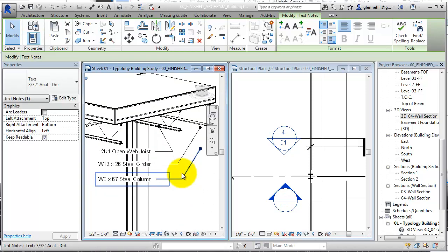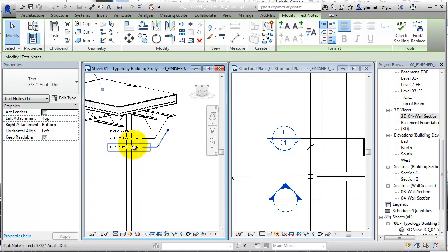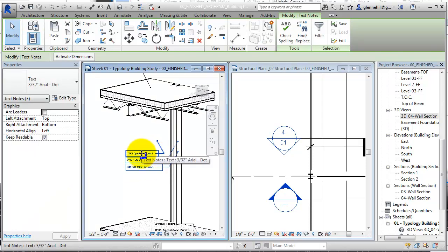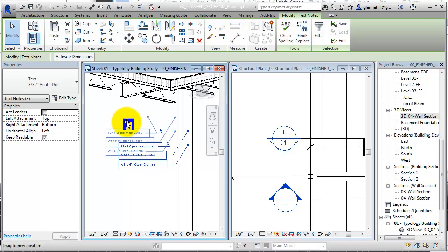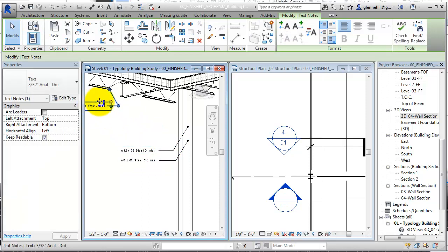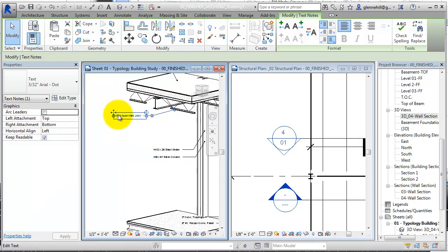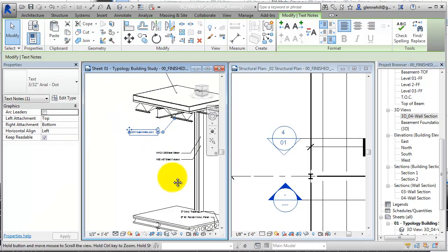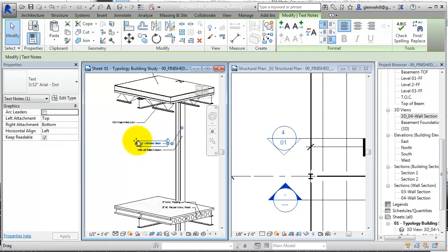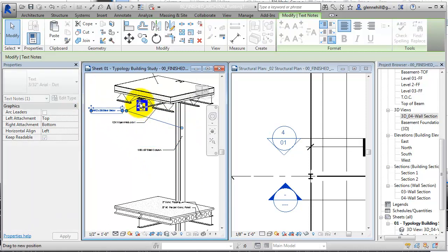Okay. In the case of the structure, probably want to keep most of that detail. I'm going to go Control on the structure. So once again, this is open web, so I'm pointing to my open web joist. Oops. So I might do that. Point to my open web joist. I've got my column there, girder, and the girder is now up here. So I'm going to point to my girder right there.